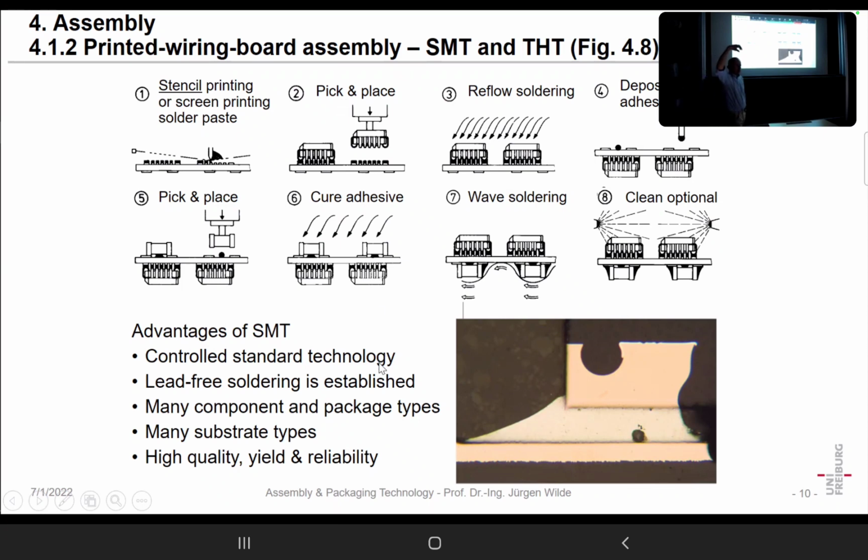Devices are set by a machinery, which is a so-called pick and place machine. Of course, it's an automated machine. There are two types of, let's say, positioning. One is you just program some coordinates and you know these coordinates are correct, and then it puts them there. But if you gave wrong coordinates, of course, you place it in the wrong place.